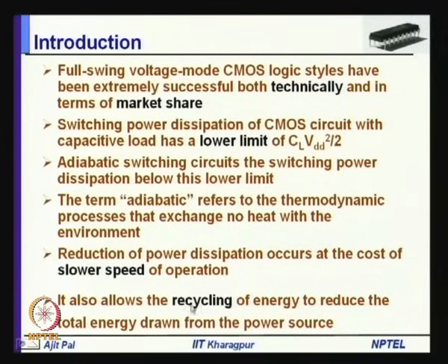Moreover, it also allows the recycling of energy to reduce the total energy drawn from the power source, and another approach which is being followed in adiabatic circuits is to recycle the energy. That means whatever energy has been transferred from the power source to the circuit will be transferred back to the power source after some computation is done.